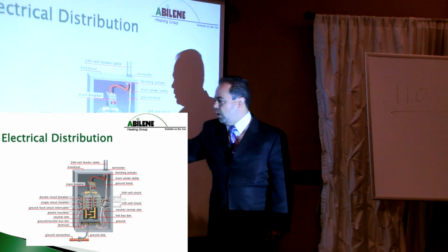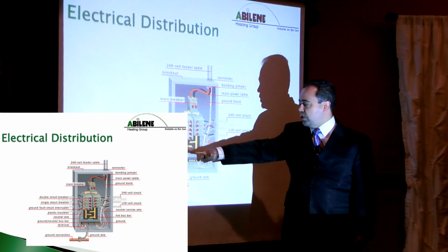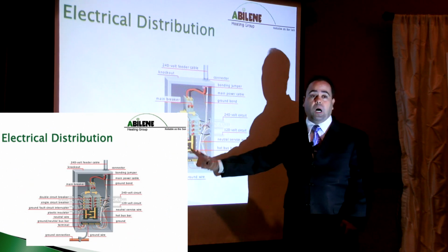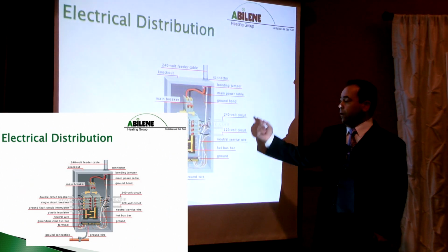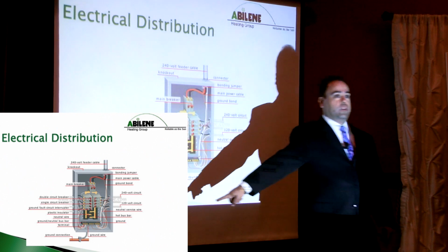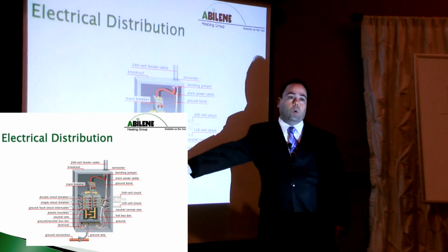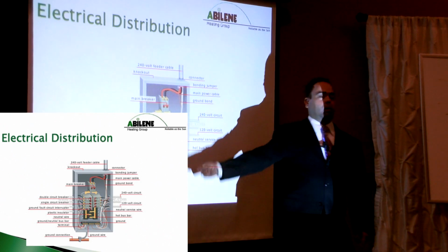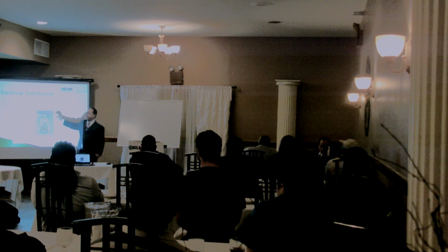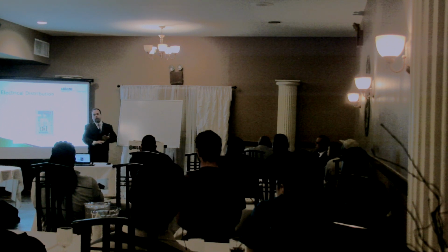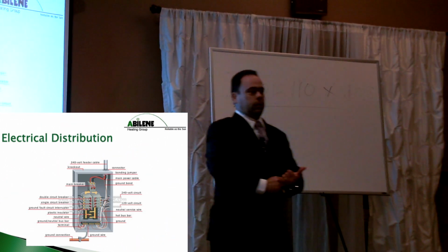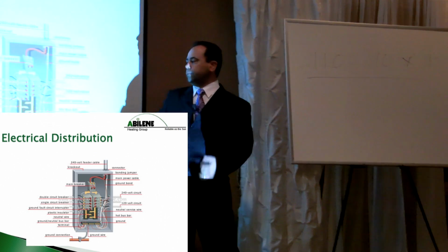This is our neutral bar, okay, which gets connected to ground, but it's not a ground. It just gets bonded to ground so that if there is a short to neutral, it goes into the ground. All right? This only happens at the main service. You don't join ground and neutral anywhere else after the main service, which means at this main breaker. Downstream of that main breaker, you never ever connect neutral and ground again. Okay? It's only at the service.